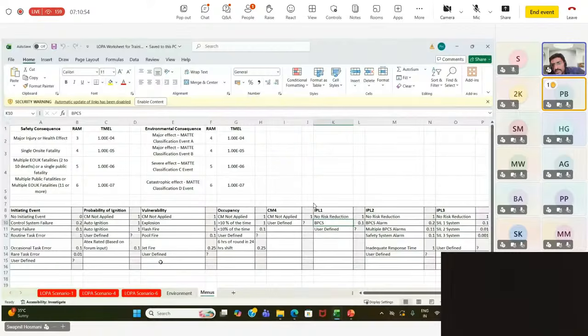So here you have multiple. Suppose you had multiple BPCS alarms, so that can create confusion to the DCS operator. So in that case, there is a slightly lesser reduction they have considered. So typically there are different definitions for different scenarios, but for our applicability, this BPCS alarm, which was 0.2, is where you get this value from. Okay.